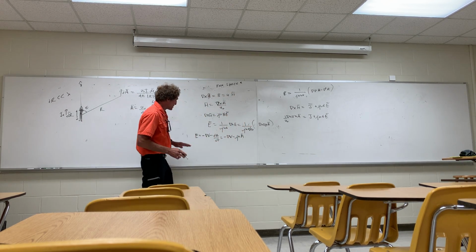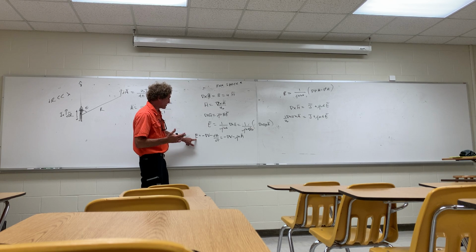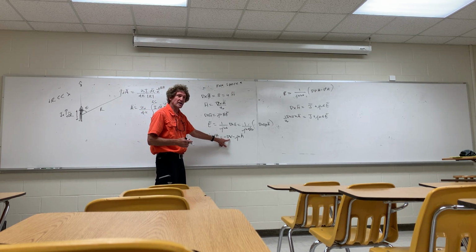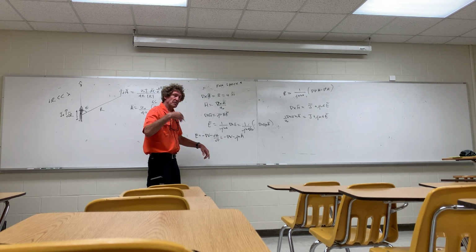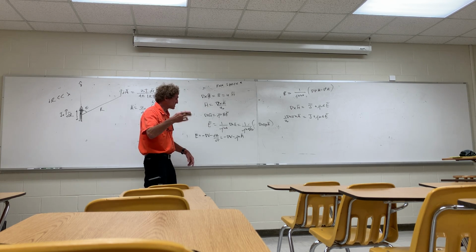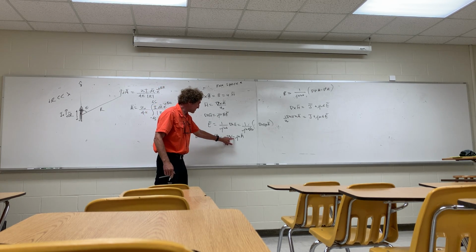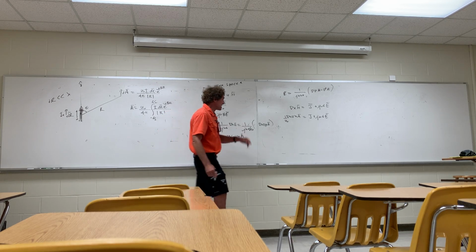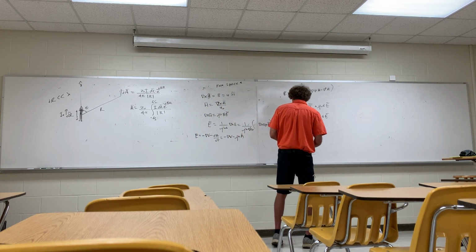This isn't in this book, but remember for electrostatics, the E field is minus the gradient of the voltage. Do y'all recall that? E is minus the gradient of the voltage. And when you have a time varying phenomenon that causes electromagnetic propagation, you have to add on minus j omega A.